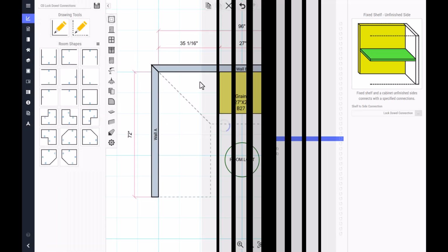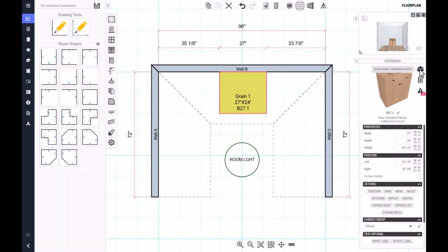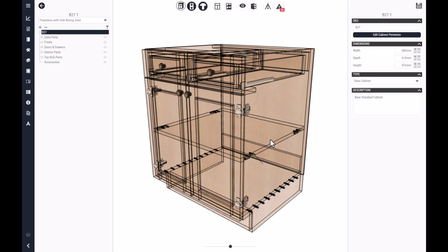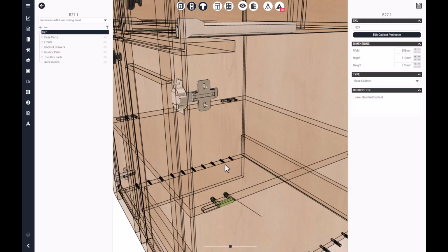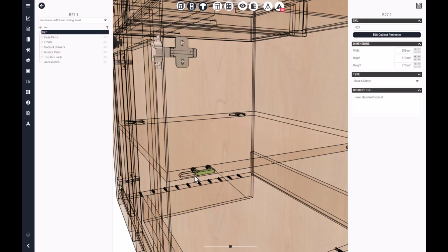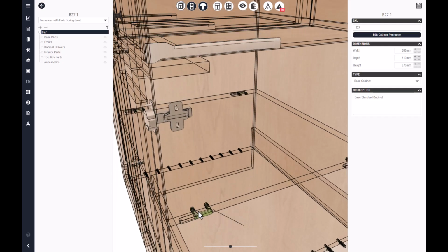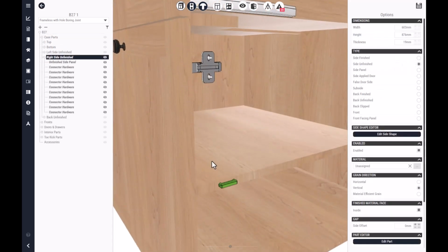Generate a test cabinet, open the wireframe, and turn on Show Processing. For channel lock, verify the selected channel lock shape, the keyhole style routed profile, the locking direction, and the lock dowel pinholes. Here we can confirm that the connected part moves in the intended direction to lock and can move in the opposite direction when the joint needs to be disassembled.